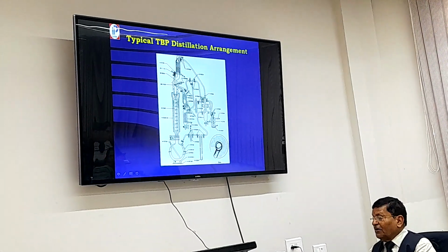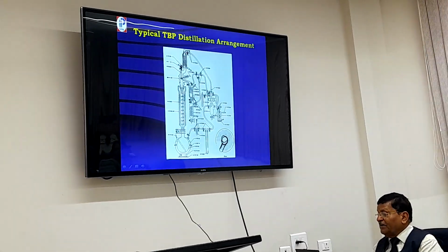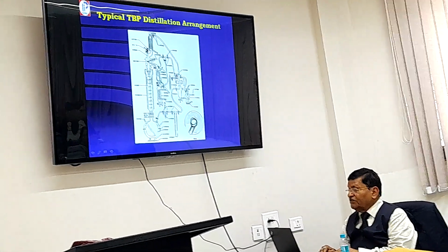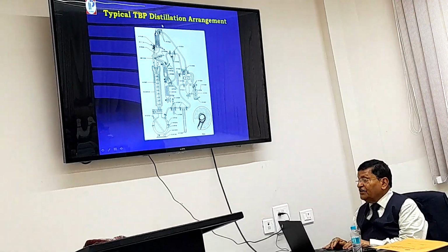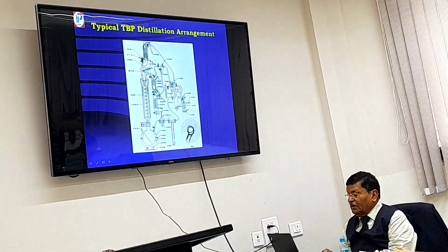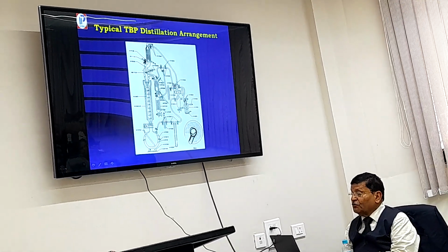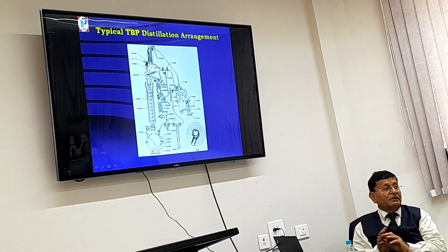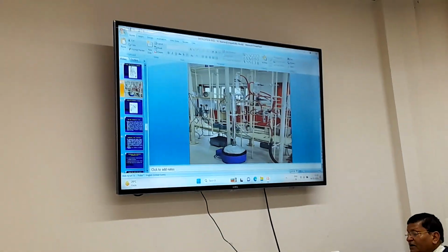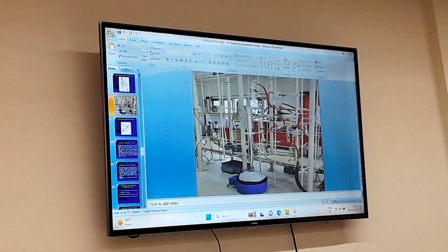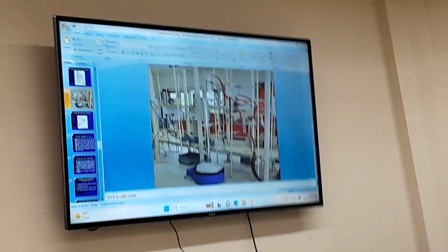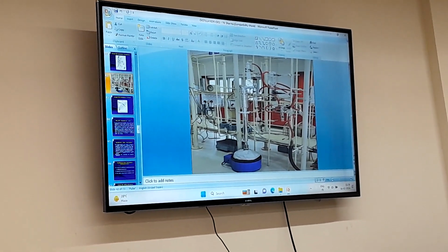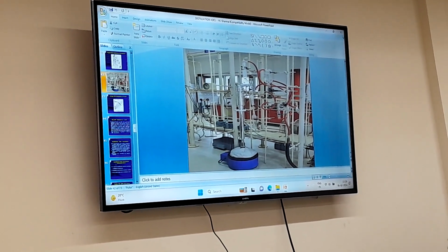Regarding the valves, first you disconnect the vacuum: you open this three-way valve and stop over here. You disconnect the vacuum and measure the pressure. And this is the solenoid valve with which you maintain the reflux ratio of 1:10. Here it opens. It's a magnetic device which rotates like this. When it starts from here, it touches here. At that time, it opens the solenoid valve.